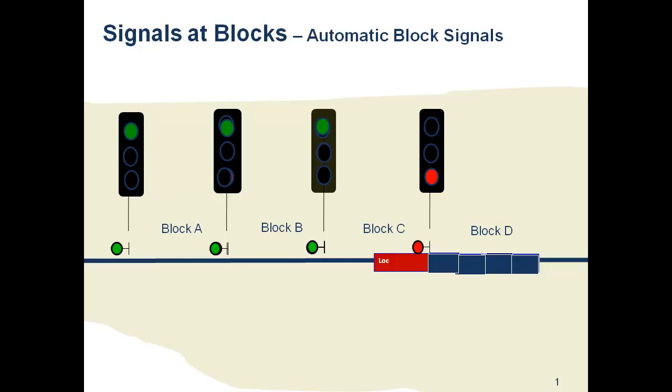A break in the rail, a lightning strike, a fuse that breaks, a piece of dragging equipment, and yes, even a train. And all of these will cause the signal behind the event to change red. In the diagram above, something in Block A has broken the flow of electricity in Block A. The red signal appears between Block A and B, with a downstream yellow between B and C. At this point, the train's personnel focus on the events down the track, perhaps a half mile to a mile away.